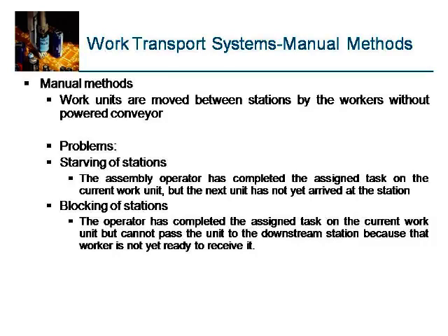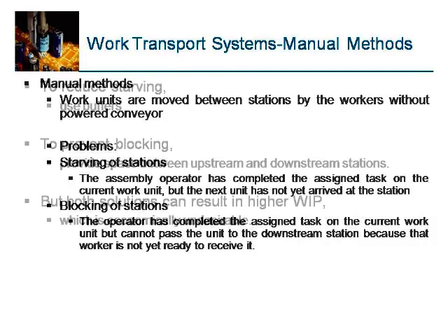This is called the blocking phenomenon, blocking of station. The operator has completed the task on the current work unit but cannot pass the unit to the downstream station because that worker is not yet ready to receive it. This is called blocking, and thus this person is not able to do the work further.